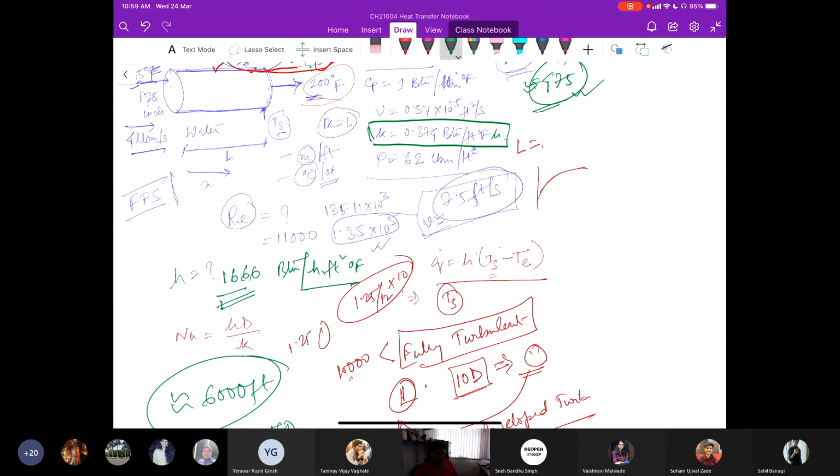Those who forgot that part, let me quickly tell you that the units are the representation of dimension. So dimensionally homogeneous means I can write, say, U2 equals U1 plus gt in the conventional manner, where U is meter per second. But then again here, if t is in minute or hour, this equation is still valid because it is dimensionally homogeneous. But during calculation, you have to convert this minute to hour or second, whatever the unit in which the velocity is mentioned. That is called consistency in unit.